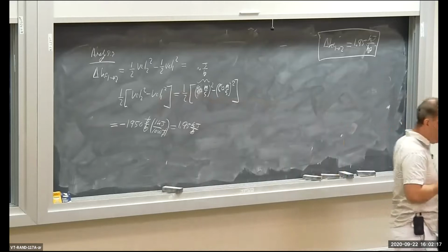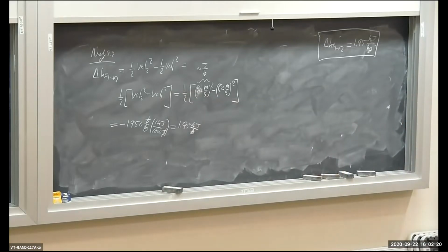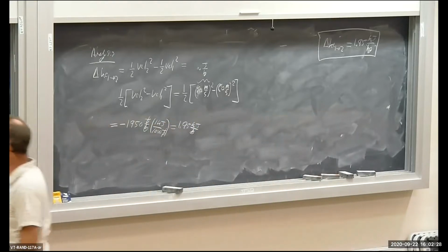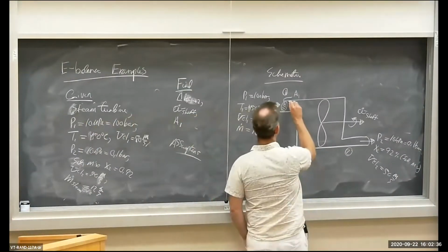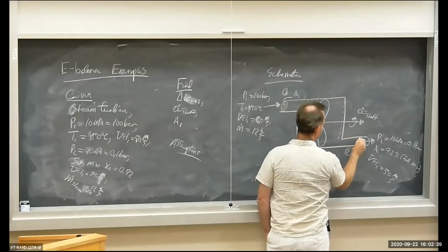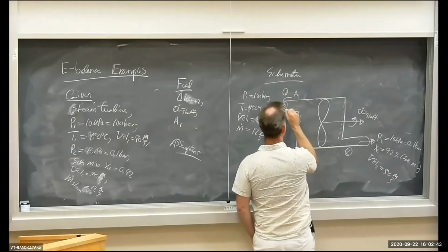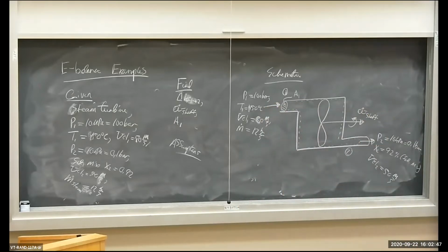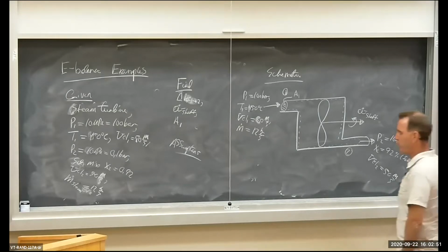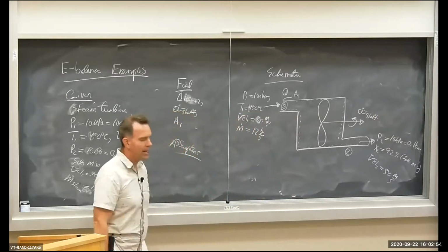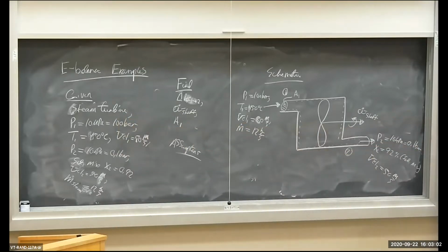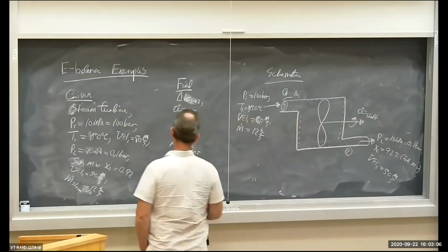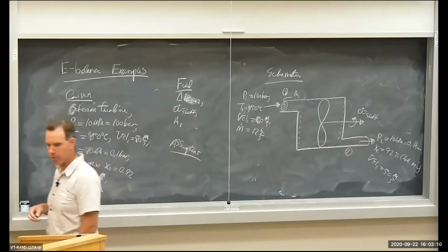All right. Now I want to calculate the shaft power or power produced by this turbine. Well, first of all, let's define our system. Before we get too excited here, let me define my system. Clearly an open system, I'm going to make the inside of my turbine the system. So the shaft is delivering shaft power by the system. It's producing work, so it's by the system. Clearly an open flow device with a single inlet at location 1 and a single outlet at location 2. Single inlet, single outlet, producing shaft work. One other little thing here. We'll wait for the other little thing, okay?